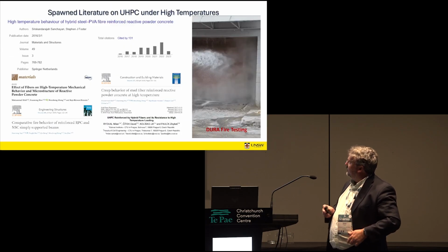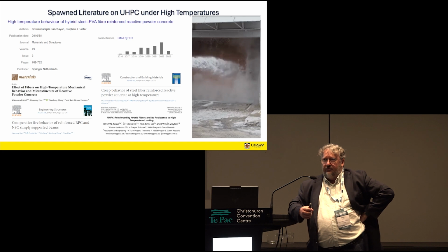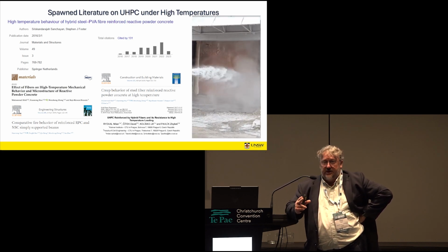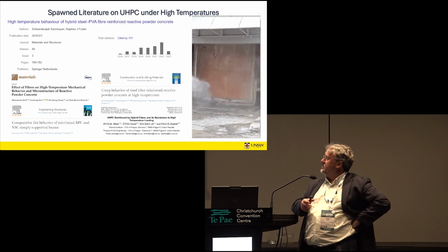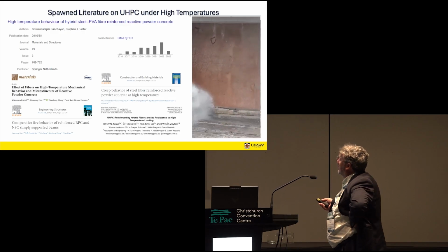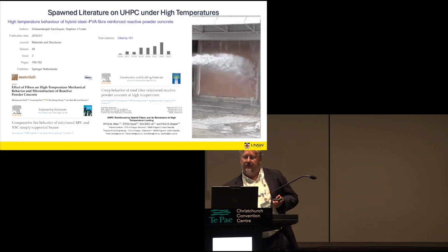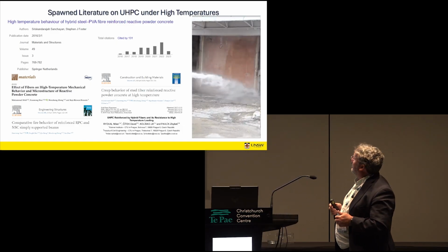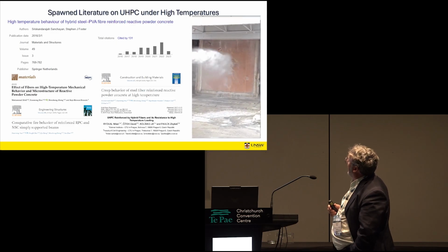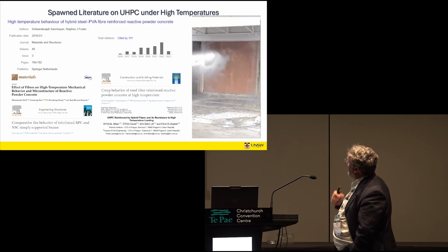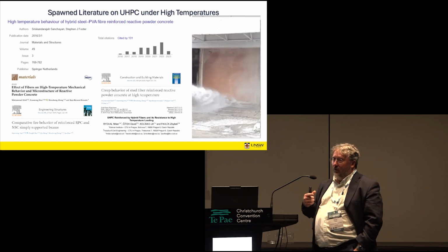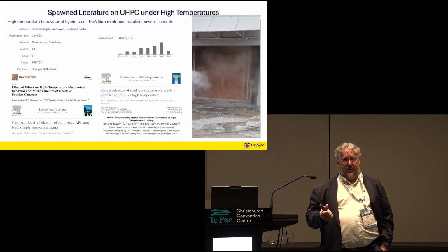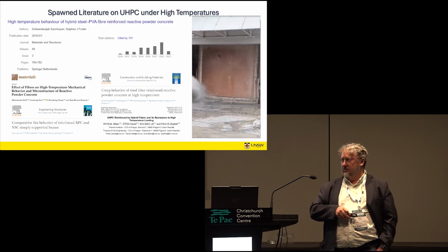I will go through this one because one of the other aspects is fire. It's really, really important in these materials, but just to show we can use the same technologies that we do for high-strength concretes. And if I can click on this figure, this is one of Jackie's fire tests. There's some sound with that. It's a big roar, but obviously we're not hooked up to speakers here, showing that you can use micro-synthetic fibres to also control the spalling of ultra-high-performance concrete. So if you have a fire situation, you need to take that into account as well.